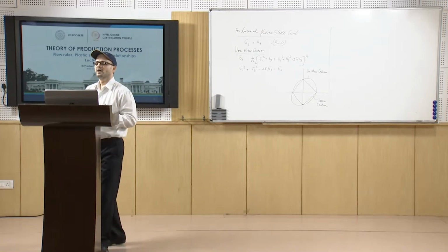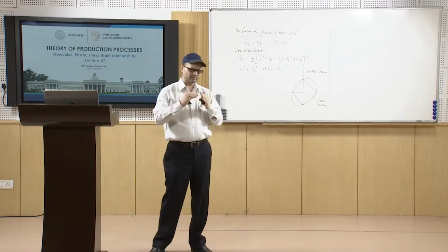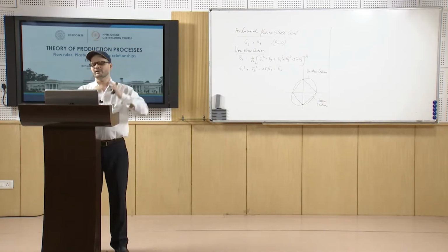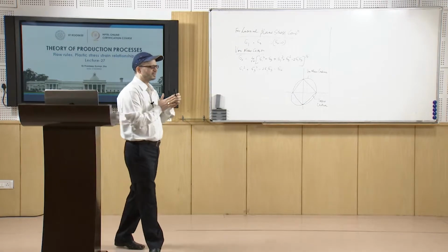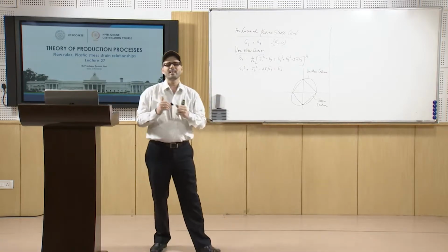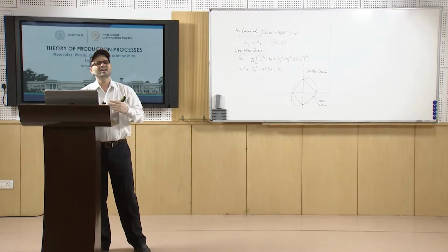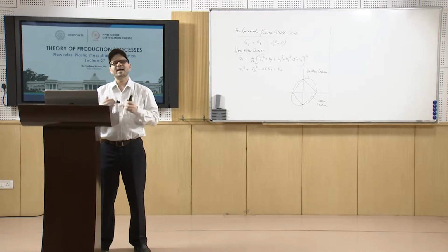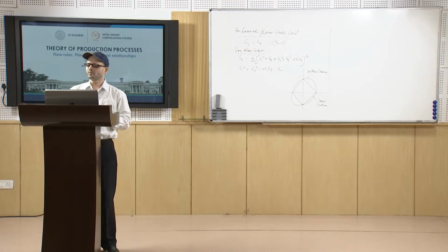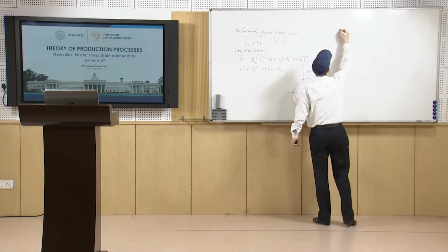Now, shear stress is the stress which is acting on the regular octahedral faces. Each face on which stress is acting can be resolved into two components. So, we are talking about the octahedral stresses. This octahedral stress has a resolved shear stress component and a normal stress component.